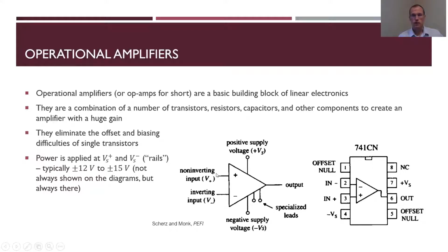So you have some voltage coming in and then some voltage coming out, and that voltage coming out is generally amplified. These are usually given on an IC chip, a little rectangular chip with 8 different leads. We'll see a picture of that in a minute. And then you have different leads for which pins connect to what in terms of coming in and coming out. So we have the output pin, input pins, and my voltage to power the op amp, positive and negative as well.